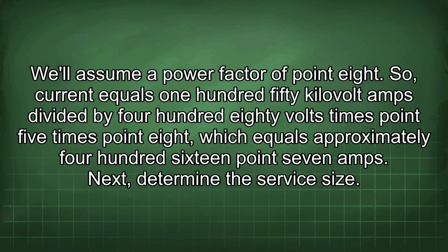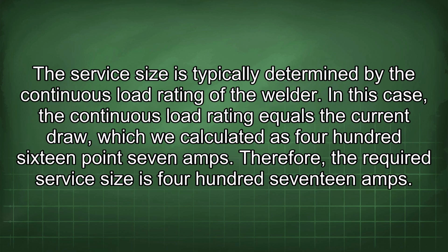Next, determine the service size. The service size is typically determined by the continuous load rating of the welder. In this case, the continuous load rating equals the current draw, which we calculated as 416.7 amps. Therefore, the required service size is 417 amps.